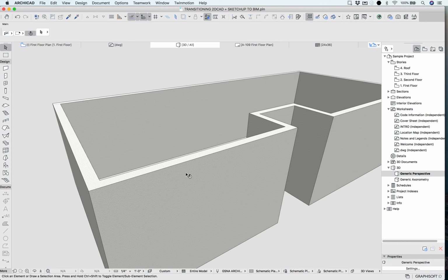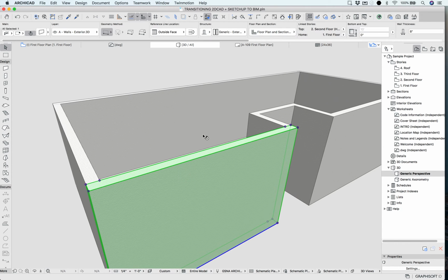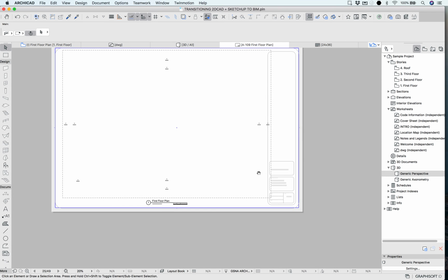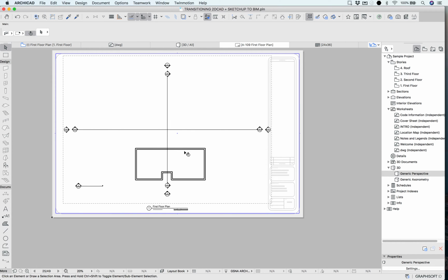And then this wall can be transitioned, the single wall, without deleting it, into other more defined elements within my project. So it really just keeps me so that I'm not really worrying about what's developing. From a preliminary standpoint, we've only done a couple things, but that information appears within my floor plan views. I have my 3D model, and everything will be updating simultaneously.